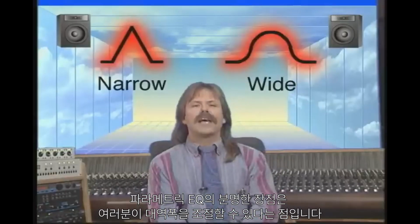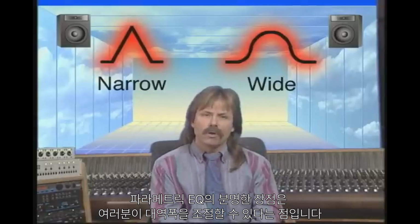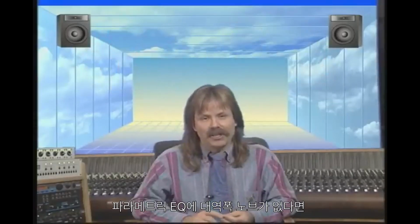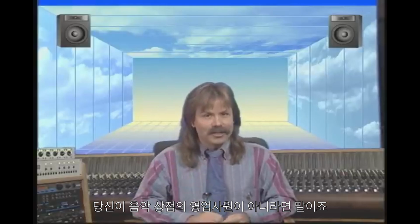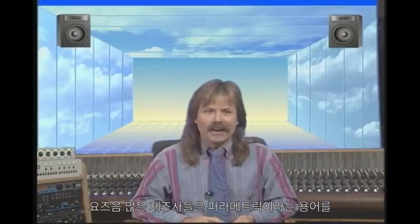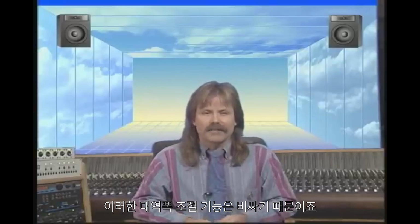The obvious advantage of a parametric is the control you have over the bandwidth. If a parametric doesn't have a bandwidth knob, it isn't a full parametric, unless you're a salesperson in a music store. These days, many manufacturers are using the term parametric to refer to a paragraphic or semi-parametric, which has no bandwidth control. Those bandwidth controls are expensive.